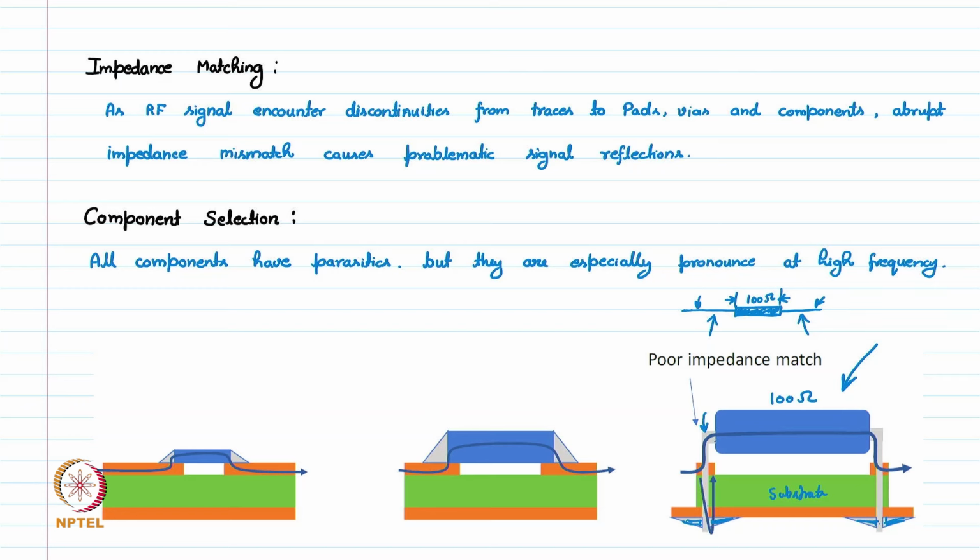If these connecting wires are long, they offer parasitic capacitance, resistance as well as inductance in the path. So when the signal travels through these wires, it experiences these parasitics, and the signal will degrade. Moreover, this extra length can also act like an antenna or stub at higher frequency. So this is a poor design for RF.